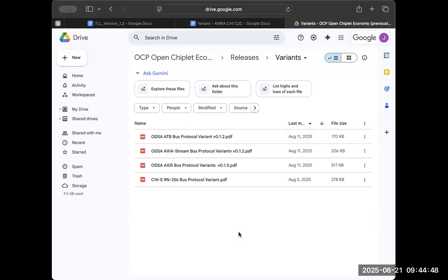I don't think there are other ones. Some other common AMBA ones would be APB and AHB. But I think the general assumption was that those are easy to convert over to AXI, right? So most fabrics have a trivial gasket they can put there, and AXI is more capable. But again, if we did something like APB, it would definitely be fewer bits.